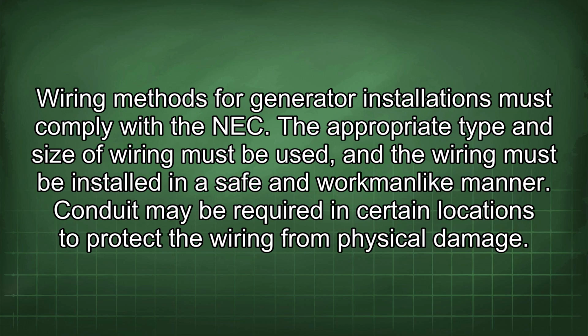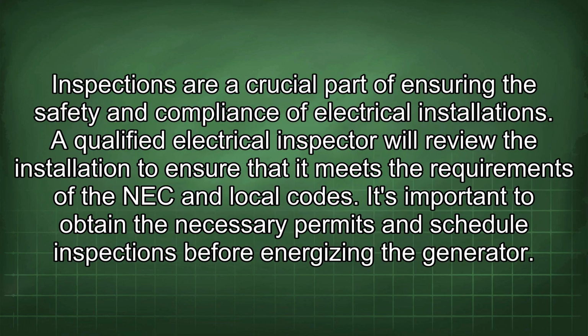Conduit may be required in certain locations to protect the wiring from physical damage. Inspections are a crucial part of ensuring the safety and compliance of electrical installations. A qualified electrical inspector will review the installation to ensure that it meets the requirements of the NEC and local codes. It's important to obtain the necessary permits and schedule inspections before energizing the generator.